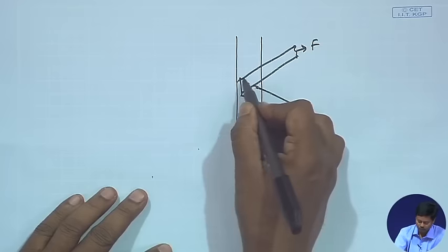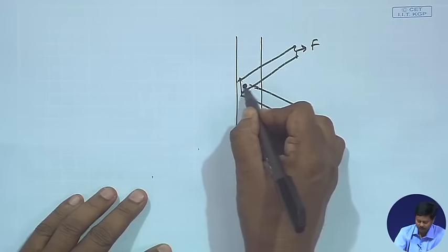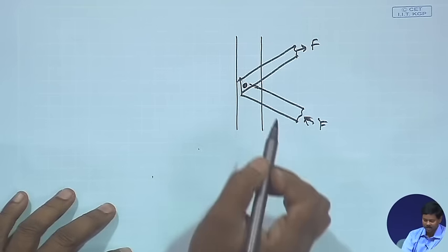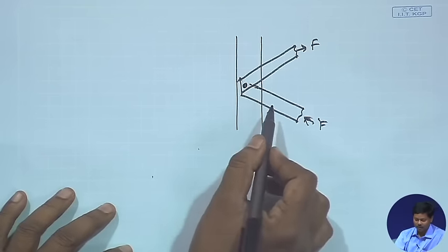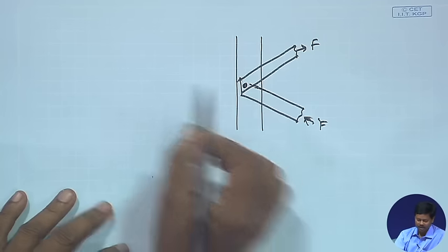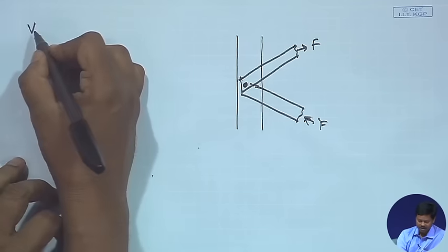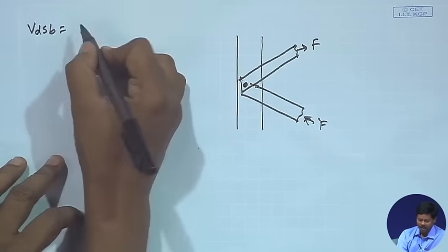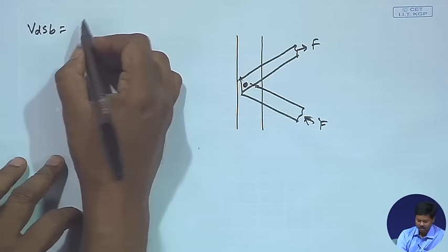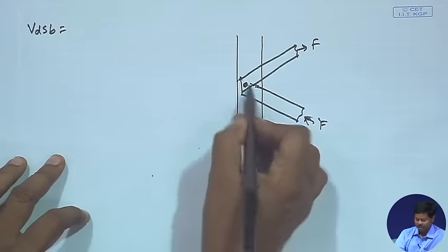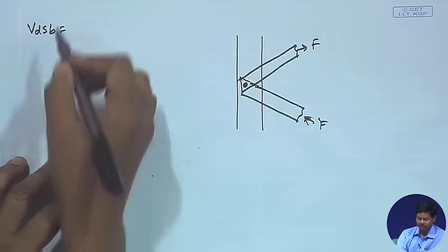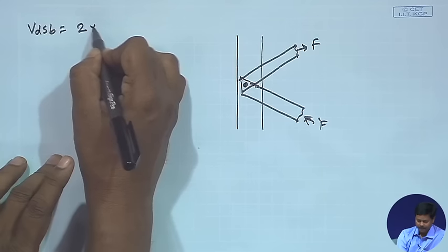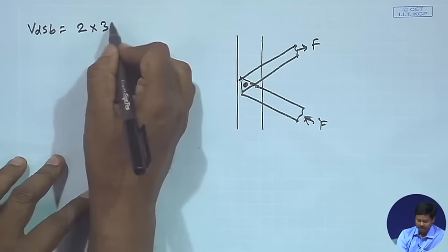Right. So, bolting will be done here, and that means the lacing in this orientation, we are making the lacings overlap each other. So, in this case the design shear strength of the bolt, VDSB, will become twice the shear strength due to single shear, because this is acting as a double shear. So, whatever shear strength we got earlier, that will be double of that, right, double of 37 kilonewton.